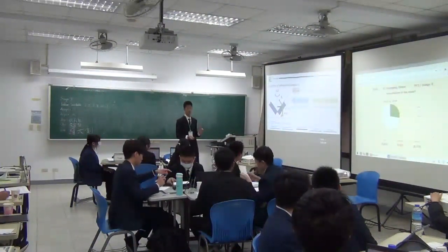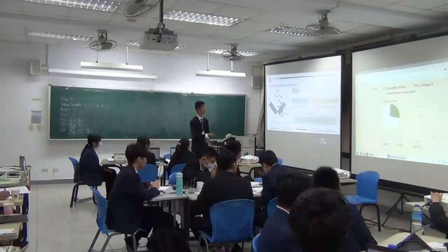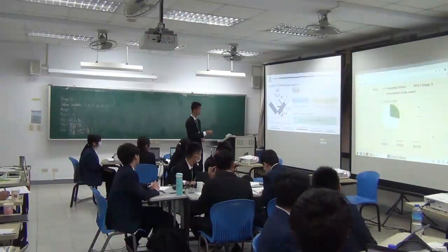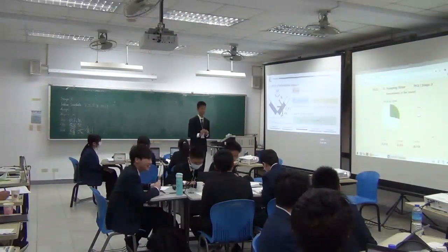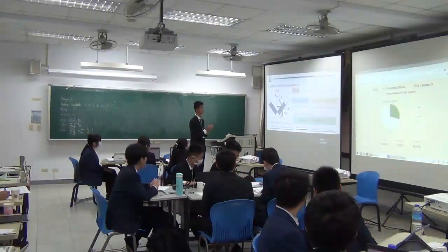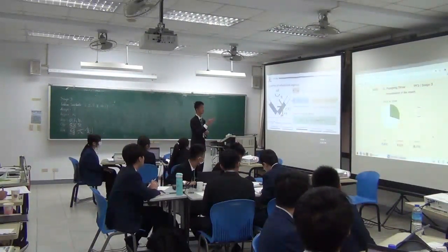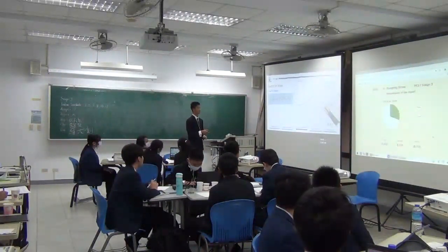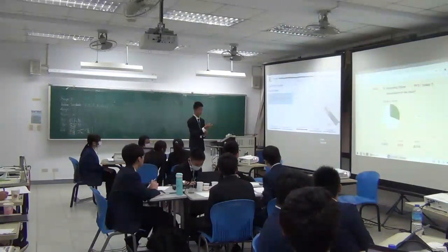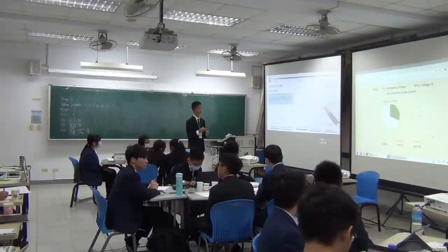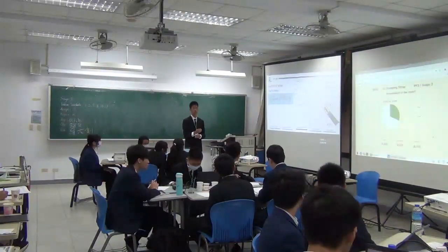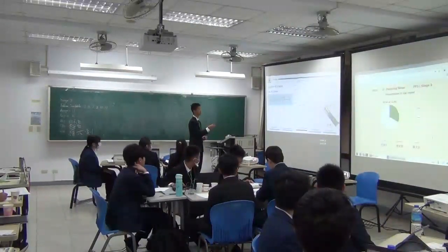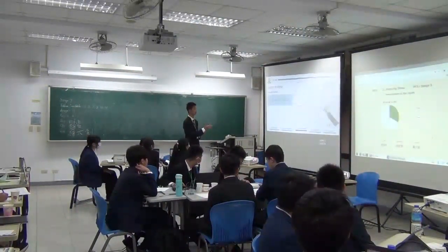Now, solving this differential equation, we can get the equation of motion of this infinitesimal water segment. Now, here I have used the constant r0c, which is defined here. And the meaning of it is the minimum initial radial distance for rising motion to happen, as you can see with the cosh function here. So here, based on this equation of motion, I can calculate the radial distance and set it equal to the radial length, which is this thing here. And I can calculate the time that the water will leave the straw, which is given by tau.